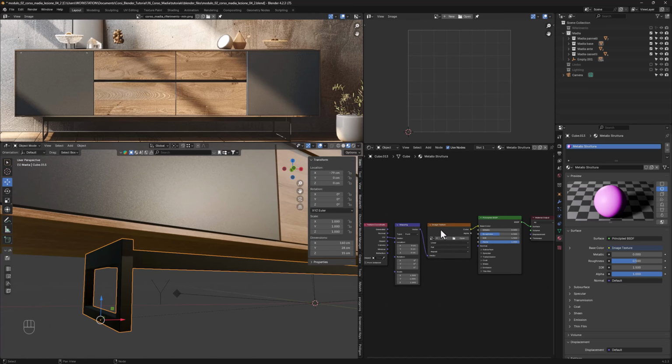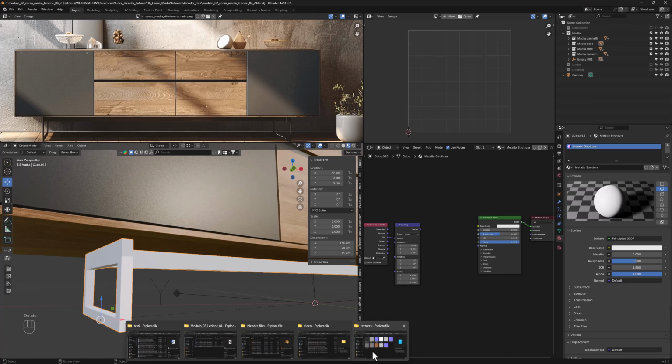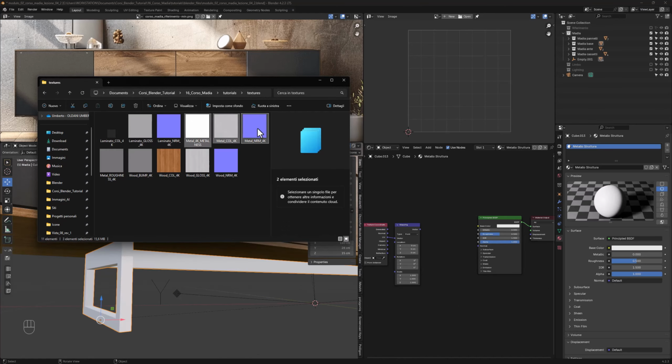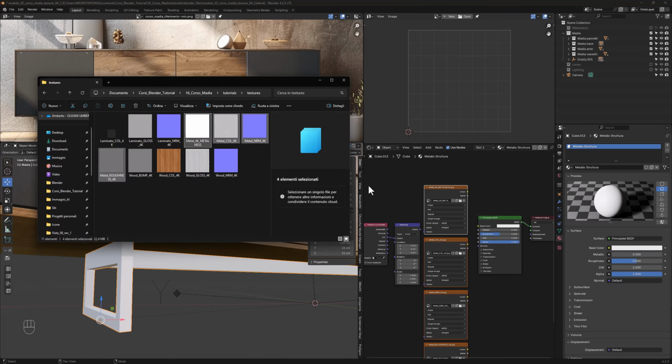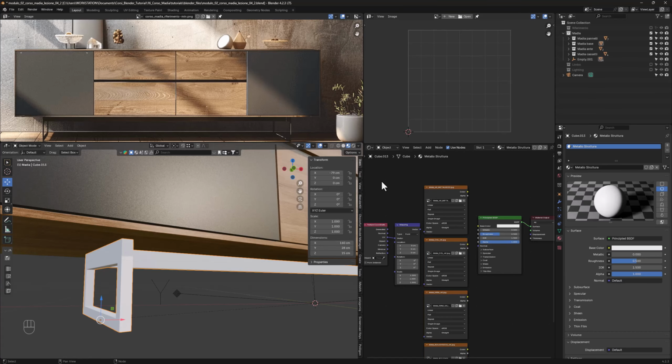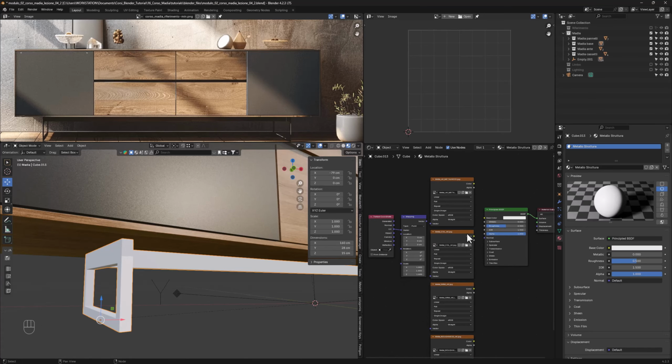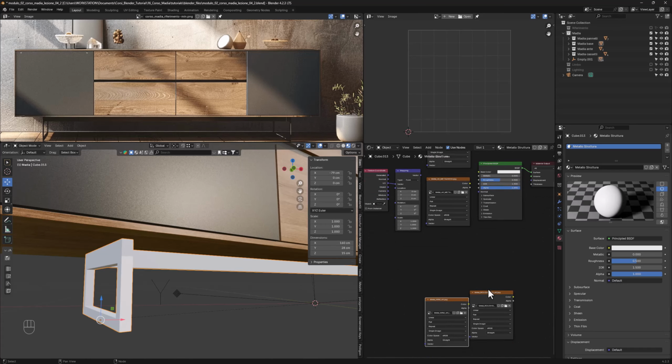Remove the Image Texture node and drag the 4 required textures, Color, Metalness, Roughness, and Normal, into the shader editor. To make the connections easier, arrange the textures in the order just specified. This will help keep the editor organized and clearly show the paths of the connections.